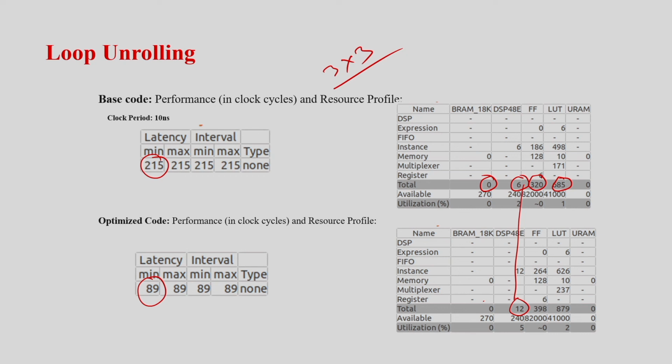So, it is not that if you just unroll you will get 3 times the multipliers. It depends on how the high level synthesis tool schedules. Obviously, I can see the increase in registers and also in combinational units, because of handling more interconnections.